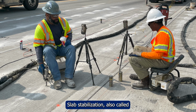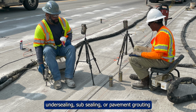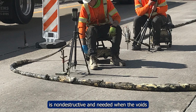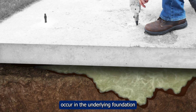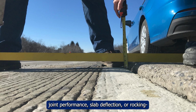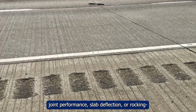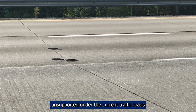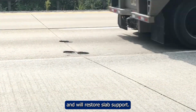Slab stabilization, also called undersealing, subsealing, or pavement grouting, is non-destructive and needed when voids occur in the underlying foundation, leaving the concrete pavement lacking a stable support system. These voids can lead to poor joint performance, slab deflection, or rocking, all signs that the pavement has become unsupported under the current traffic loads. Stabilization will restore slab support.